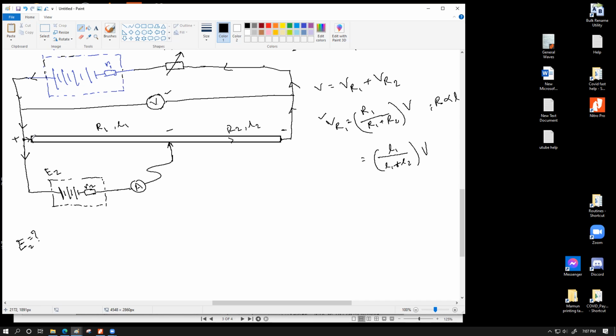Across these 2 points, from here to here, you are applying a fractional voltage that we named as VR1. VR1 is the actual potential that is available across this length of resistance, and you are connecting this unknown cell over here. I want you to have a bit of flexibility in thinking that we can move this slider. Whatever is left on the left is R1, and that voltage is VR1, and whatever is left on the right is R2, and that is the voltage VR2.